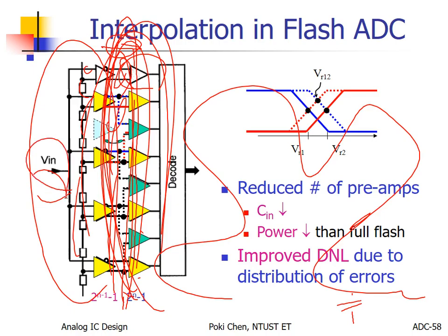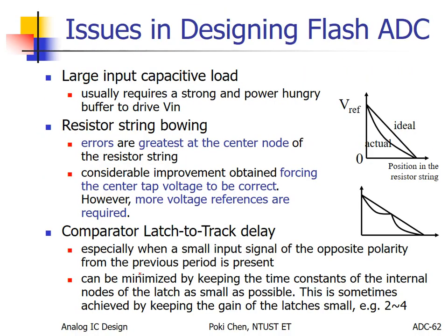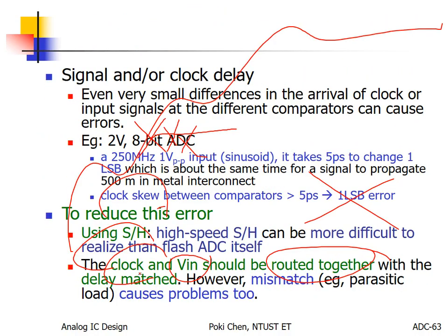For this stage, if the input arrives later, then hopefully your clock also arrives later. It is shifted to the right, or if it arrives earlier, then we shift both input and clock signals to the left, to match all of them. Anyway, that is very important for your real design.